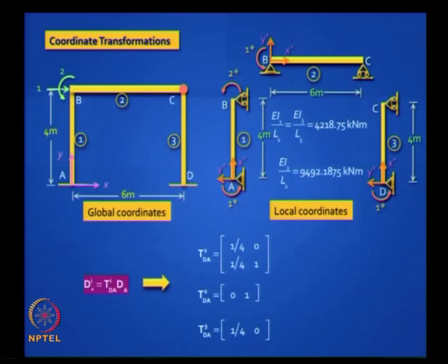Remember when we did by the conventional stiffness method, we had 5 with the hinge. Without the hinge it was 6. Here without the hinge it was 3, with the hinge it is 2. So you have D1 and D2 in your structure as your unknown rotations. Is this clear to you? The TD matrix? It just follows from the previous case. Okay, just ignore that rotational degree of freedom at C.